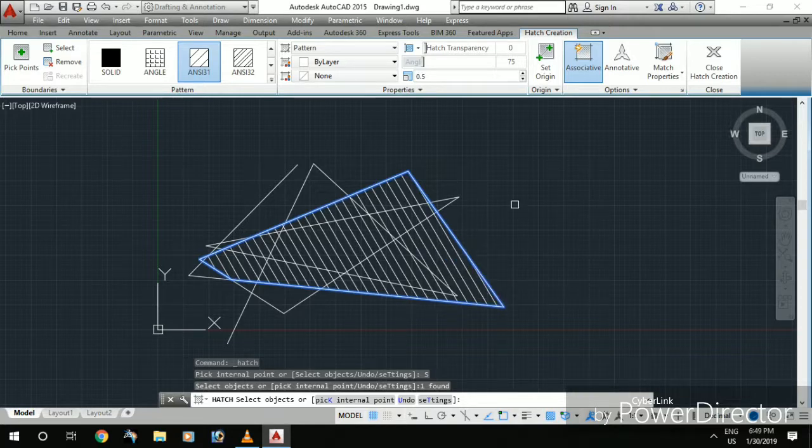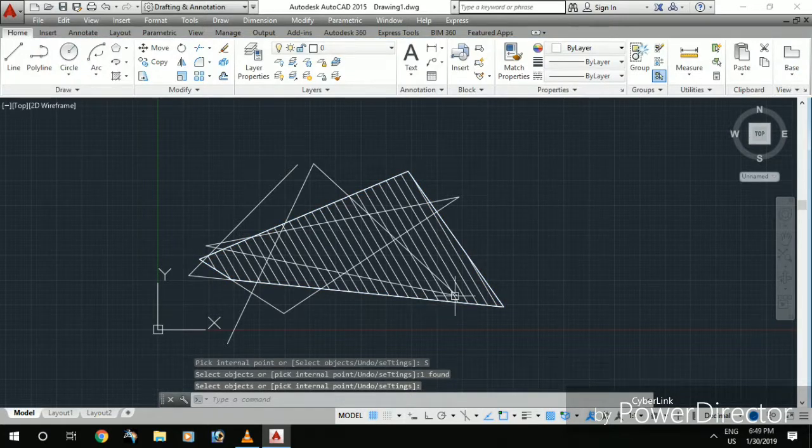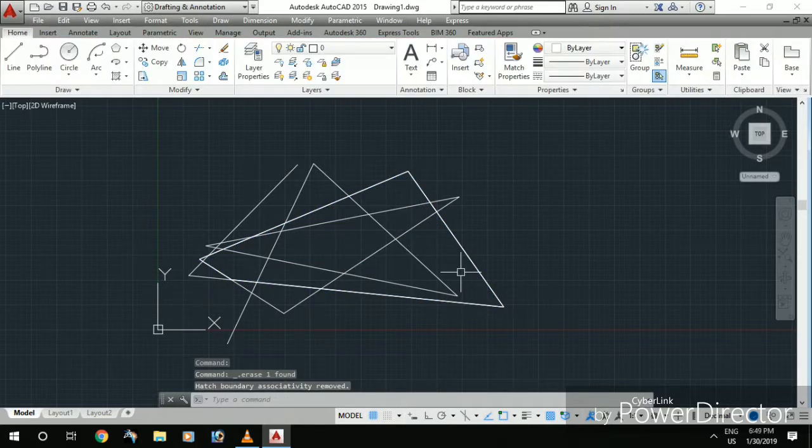In this way you can draw hatches for an irregular object and a regular object, and even transfer the properties from one object to another. It doesn't work if you haven't drawn a line or a rectangle but just a hatch. The hatch which has been made can have its properties transferred from one hatch to another. The properties transferred are only those which are applied in a hatch.